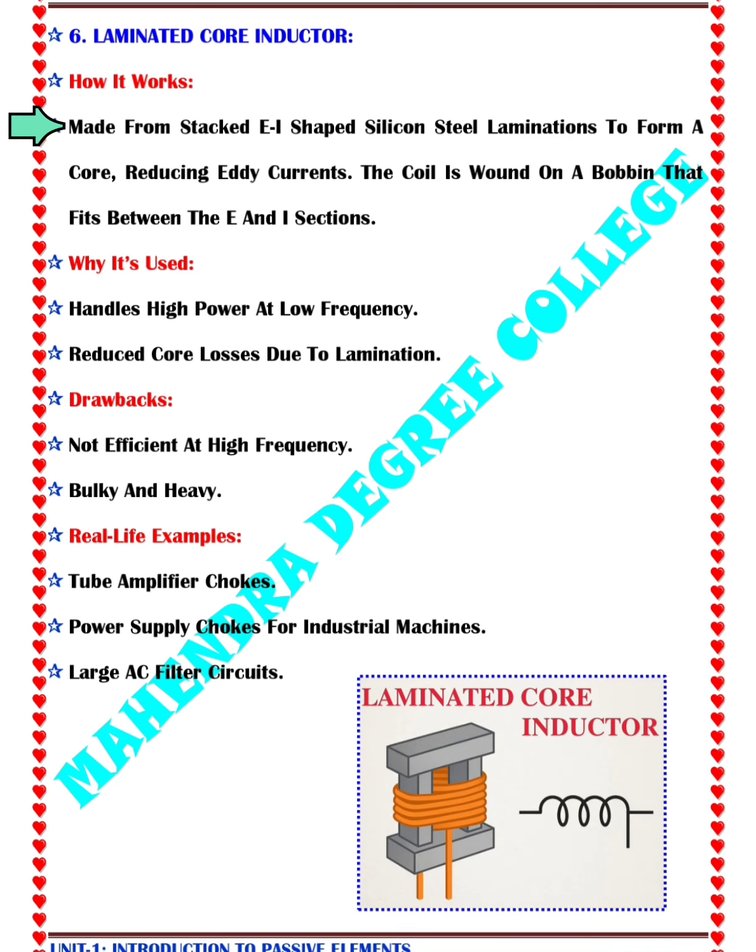The final explanation: a laminated EI core inductor uses stacked EI shaped silicon steel sheets to form the core. The lamination reduces eddy current losses and the coil is wound on a bobbin that fits between the E and I pieces for efficient operation.